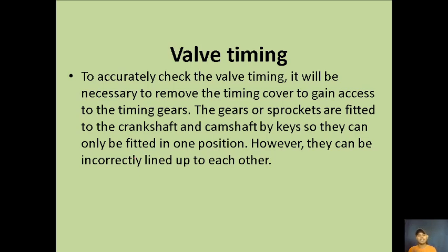Okay, so to accurately check the valve timing, it will be necessary to remove the timing cover to gain access to the timing gears. The gears or sprockets are fitted to the camshaft and crankshaft by keys, so they can only be fitted in one position.